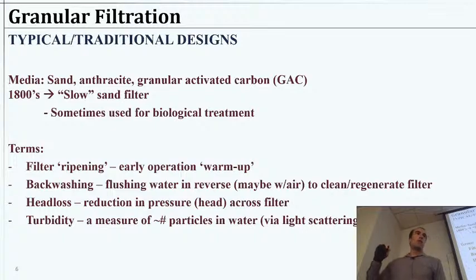How many of you have ever filled up a new Brita filter thing of water? Do you use them? You ever have that experience where a bunch of little black specks come out into your water when you open up a new one? Anybody? Okay, some. So some of you have seen that. If you open a brand new one and use it without any flushing, there's probably a few particles that come out. That's actually kind of typical. That's just some fine, small particles of that media that are loose and escaped. So you generally recommend allowing it to operate to flush some water through before you start doing stuff.